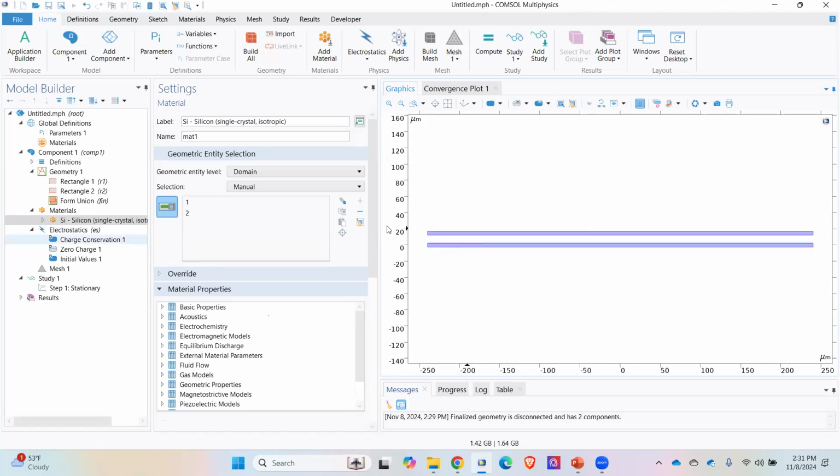Here nothing is moving, I mean your geometry is not deforming, right? So you don't worry about fixing the things. But if you have selected structural mechanics, at the time your voltage will pull your beam, so you have to fix that thing, so be careful on that. So in parallel plate, there should be one dielectric medium as well, right? So here I want to select this one as air, but if you see here outside the space, in the space that you have to constrain your design, right?